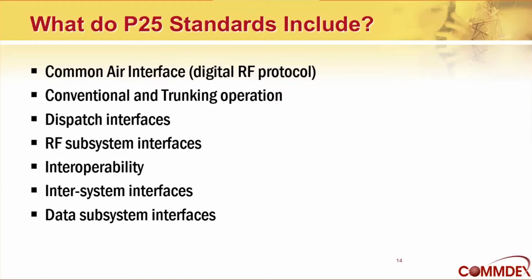Whenever you have first responders, you have dispatchers. You have to have interfaces between the radio system and the dispatch. RF subsystems. How do the various base stations talk to the system? Interoperability. How do systems from different manufacturers communicate with each other? Intersystem. How do systems interoperate at the system level? How do their infrastructures tie together if they have to? How do you bring data into the system? So all that is addressed in P25.